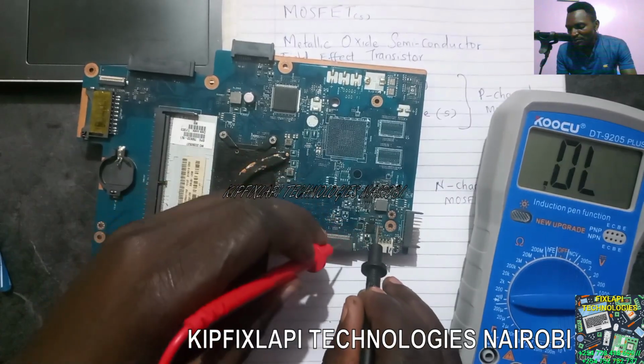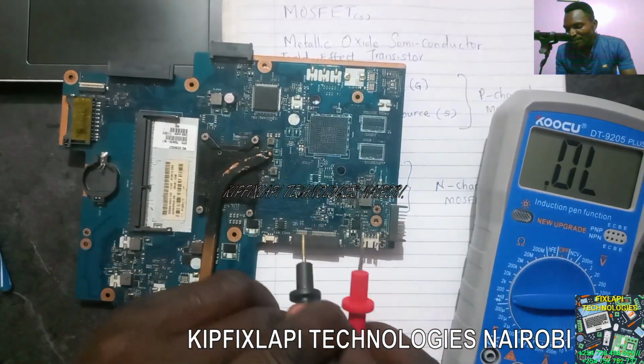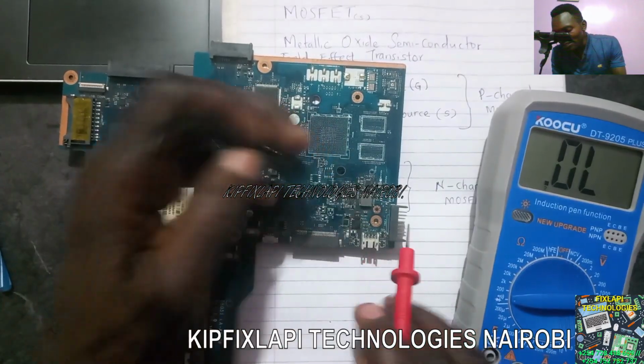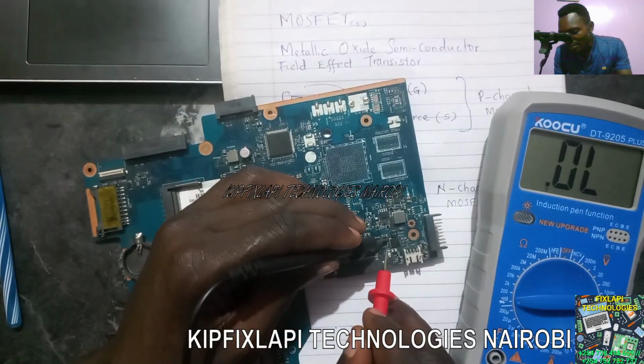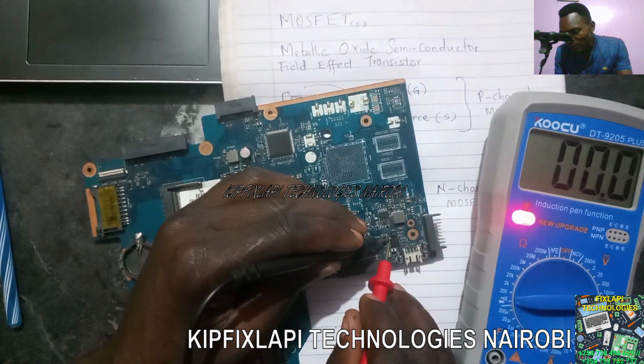So how do you know these pins are connected together? Let's test it this way, guys. I have the probes, so I can place the probe at either point. Okay, let's start from here. You see these first three are connected together. So I have this pin number 1 and number 2. You can hear. So those points are connected. What about number 3?